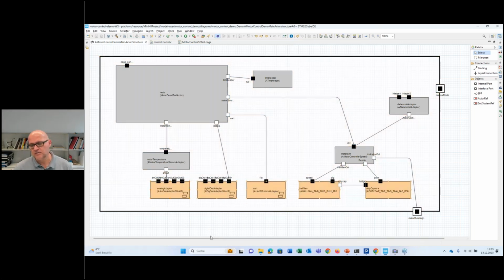Here on the I/O level, we have the analog, digital adapters, UART. Here the duty capture unit captures the 3 duty cycles, measures them, and propagates it to the motor simulation. The motor simulation runs on every duty cycle. It calculates the new speed and propagates it to the whole generator. And the whole generator generates the whole signals at these digital outputs according to the speed. So that's the I/O level.